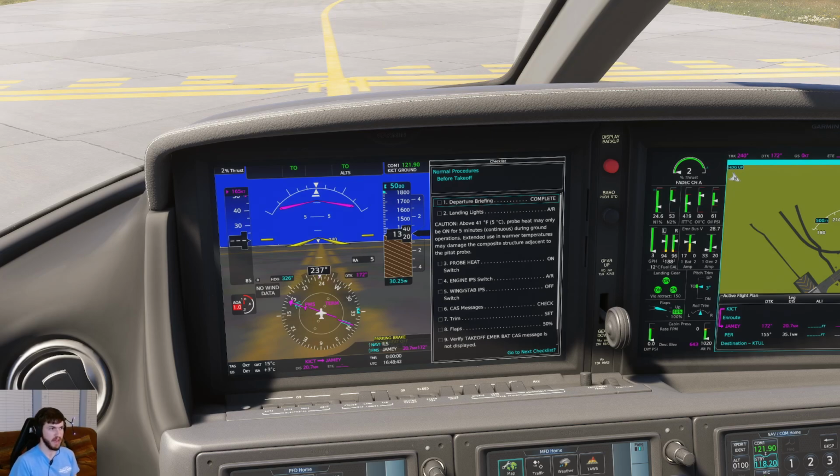Departure briefing, I'm expecting an initial heading from tower on the departure. And then we'll fly that heading and climb maintain 5,000. As far as the emergency briefing goes, on this runway, I'm going to say if we don't have 60 knots by the intersection at taxiway Bravo, which will be the first taxiway intersection that you see on our departure here, then we will abort the takeoff.